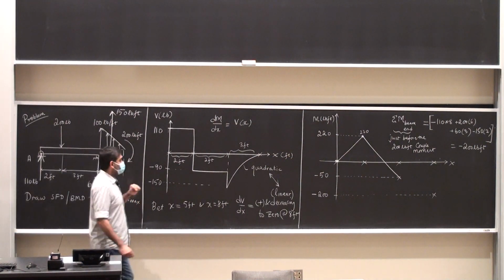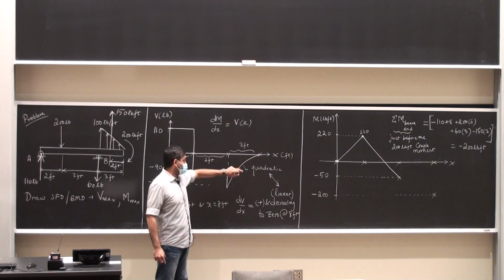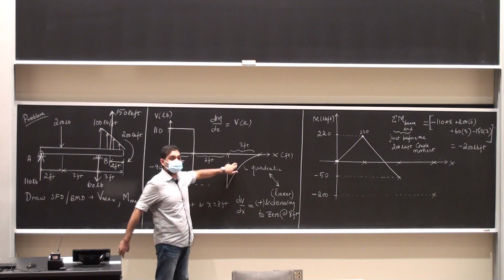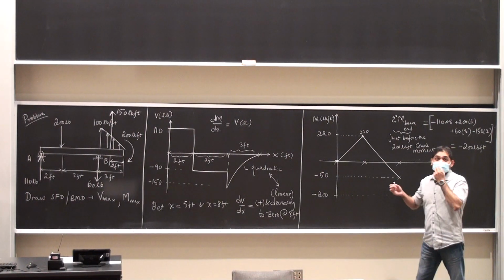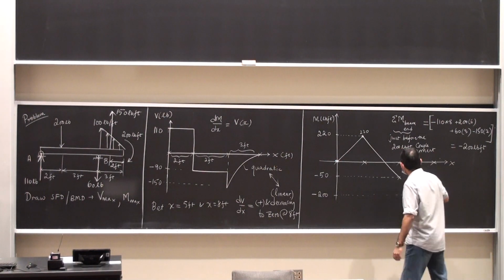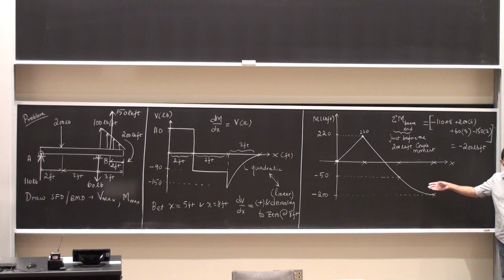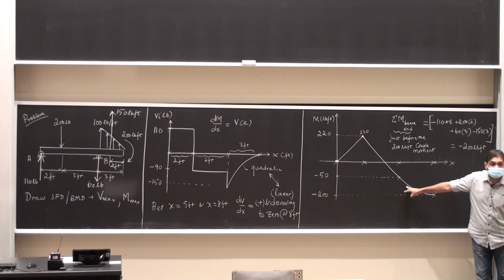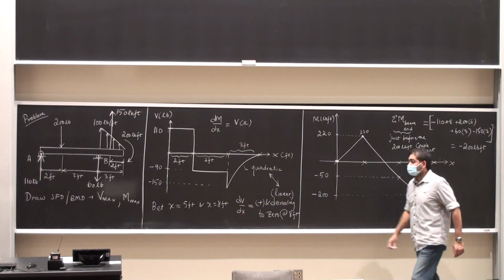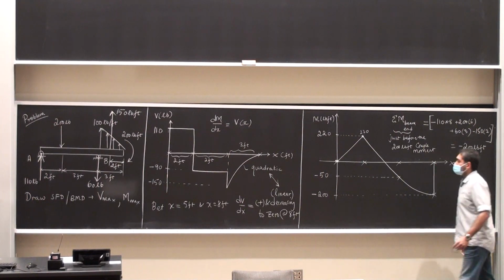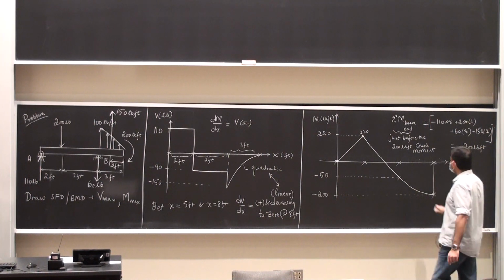Look at the shear force diagram. Slope of the bending moment is the shear force value. Shear force value is what? Is it positive or negative? Negative. Slope is decreasing, which means that I start off with the same slope that I had here. Slope is decreasing and eventually goes to 0 at the end there. So I'm going to go in the following manner on the bending moment curve. What kind of a curve is this going to be? Is it a quadratic or a cubic? It has to be a cubic because the slope of the bending moment is a quadratic. And then I go back home, because of the fact that I have a 200 pound-foot couple moment pushing me back up. Okay, so this is going to be a cubic.